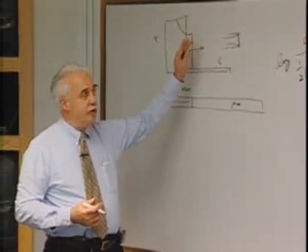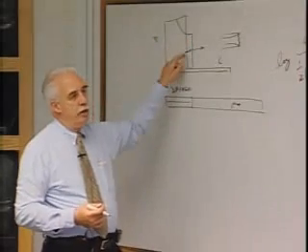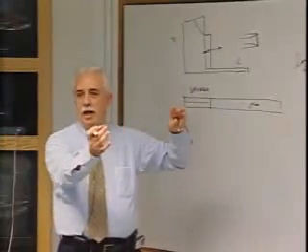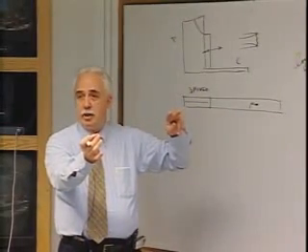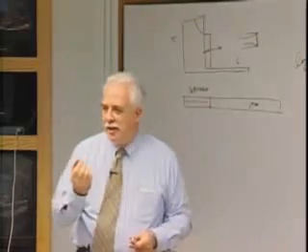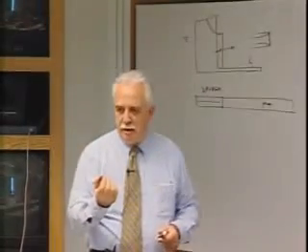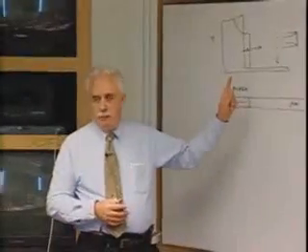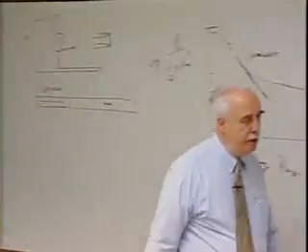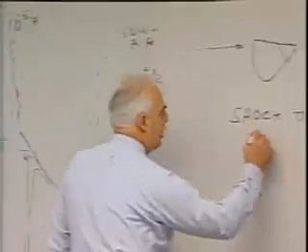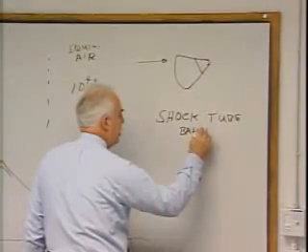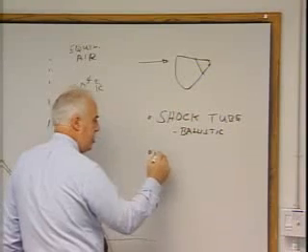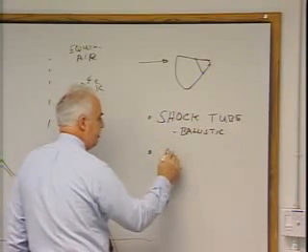There are three facilities you can get to them. One is in a shock tube. Second is a ballistic facility where you fire a projectile that looks like what you're going to fly. And that does a good simulation job, except it's very small. And getting any measurements is very difficult. If you go into a wind tunnel, you can get great measurements, but you can't get the energy. So the shock tube and ballistic facility, I'll just put this down here as it has the difficulty of measuring things. The other place you can get the energy is in an arc jet.